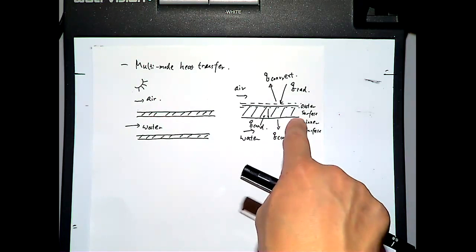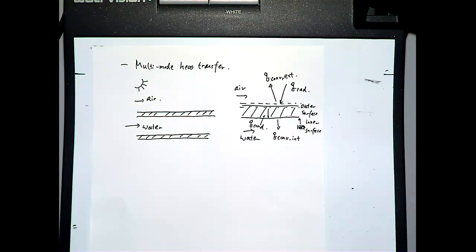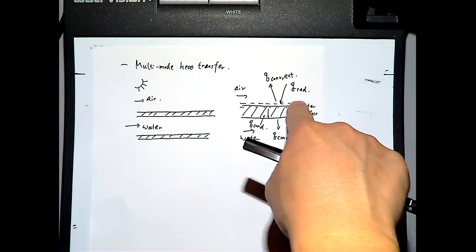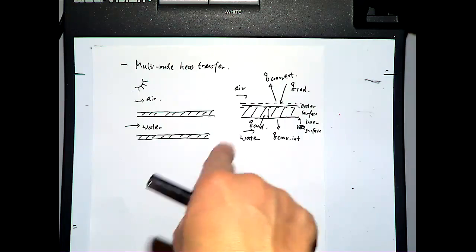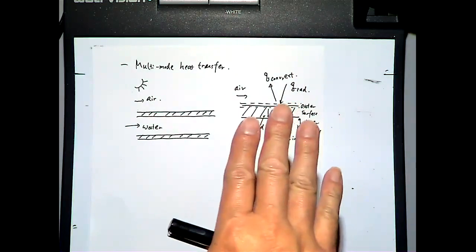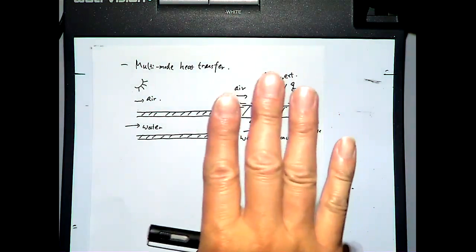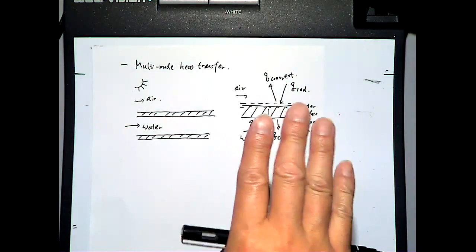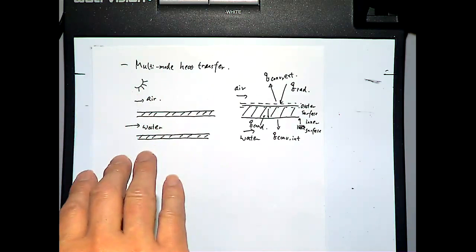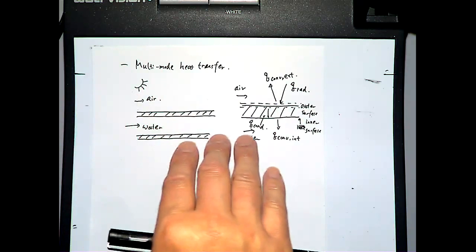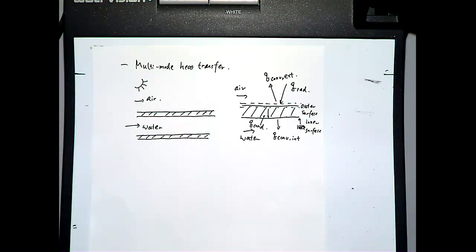And then once the energy balance is figured out, the next step is to bring in the rate equation corresponding to the different heat transfer modes, and to calculate the problem. So what I just described is the method to study the heat transfer problem. First, select an object to conduct the first law analysis, then bring in the rate equations for the calculation.